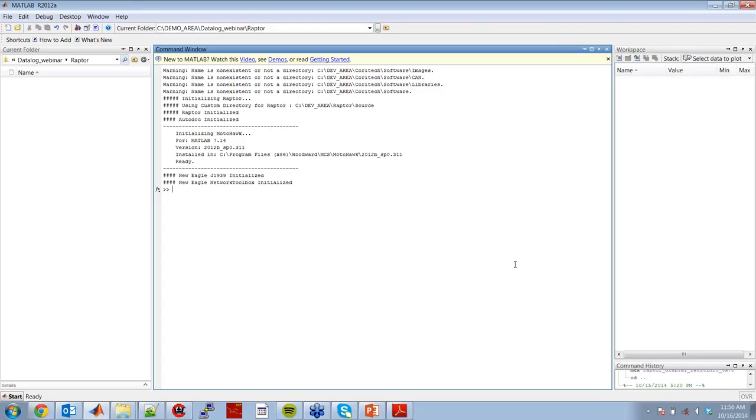If you've got DBC files, you can pull in a message. We'll kind of show that. You can pull it into the software with the DBC file in the model, and then you'll have the engineering signals, and you can use the USB blocks to write them to the USB stick. So you can kind of create your own custom embedded data logger appliance in that way.